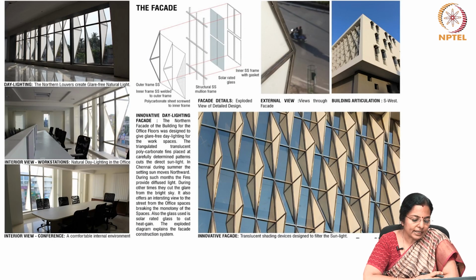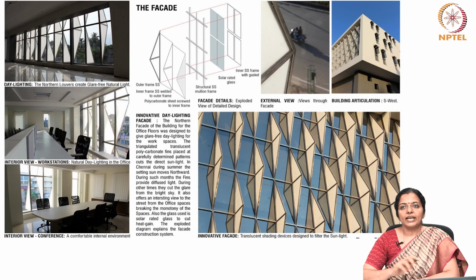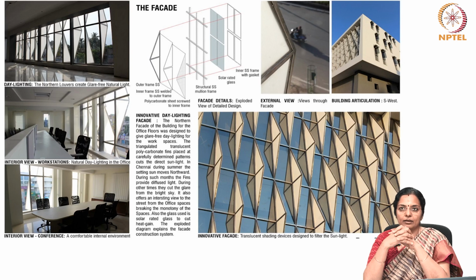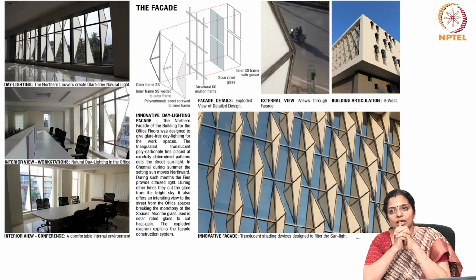Let us now look at the north facade. Now, innovative daylighting facade has been adopted here. The northern facade of the building for the office floors was designed to give glare-free daylighting for the workspaces. The triangulated translucent polycarbonate fins placed in carefully determined patterns cut the direct sunlight.